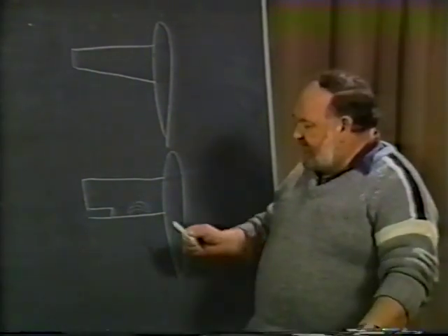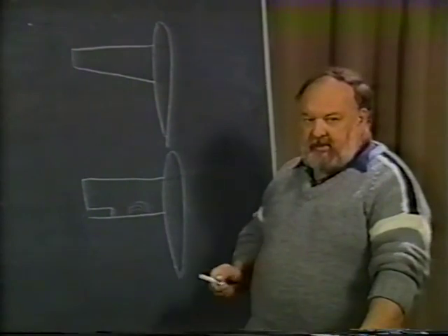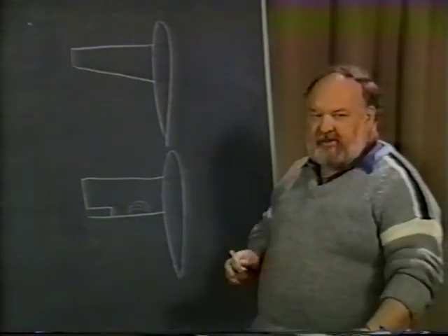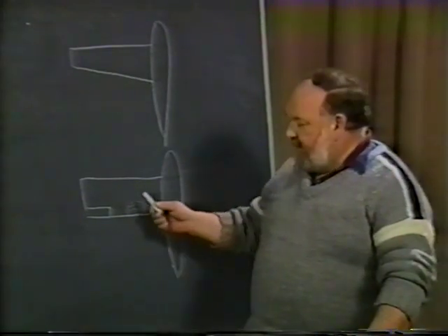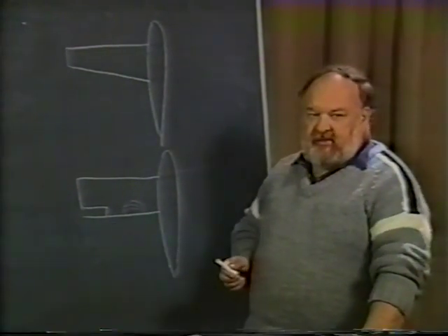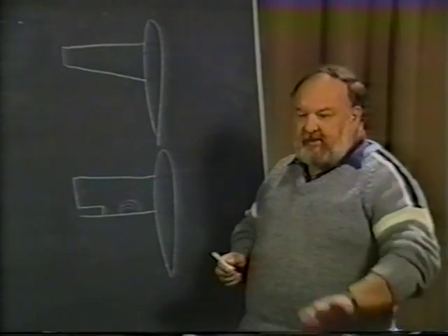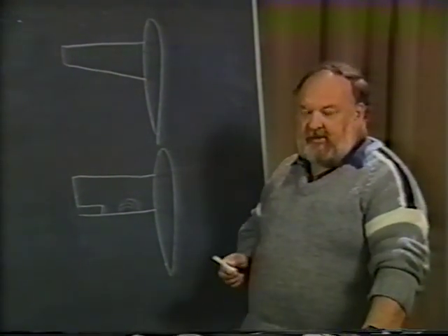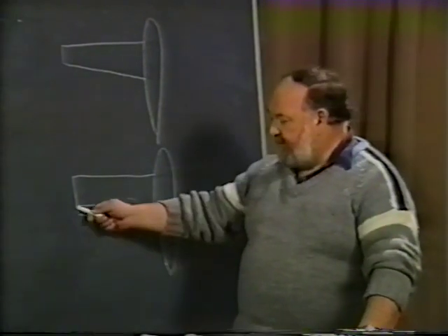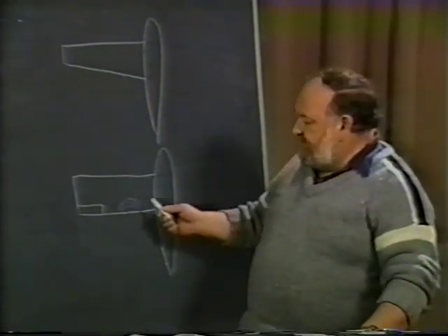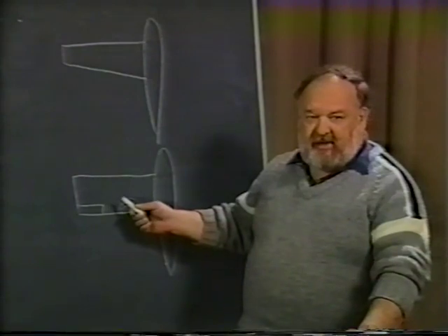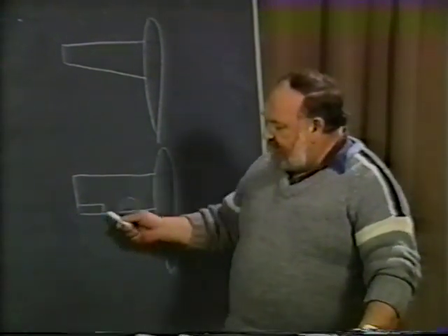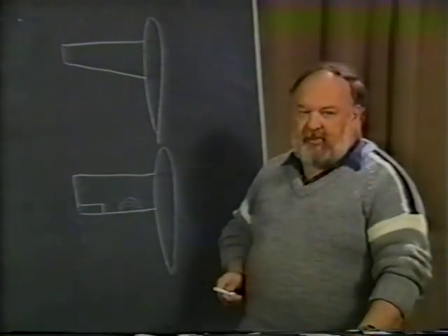If, on the other hand, it's outboard, and for any reason at all you have just a little bit of yawing of the airplane or just a little bit of turbulence or whatever might occur, and one wing section, tip maybe, stalls before the other, the airplane will have a tendency to roll, and of course this can become the onset to a spin developing. So besides that aspect of it, you also would like to be able to have some roll control, lateral control, while doing this, and therefore you want to stay away from having the stall pattern begin out near the tip.